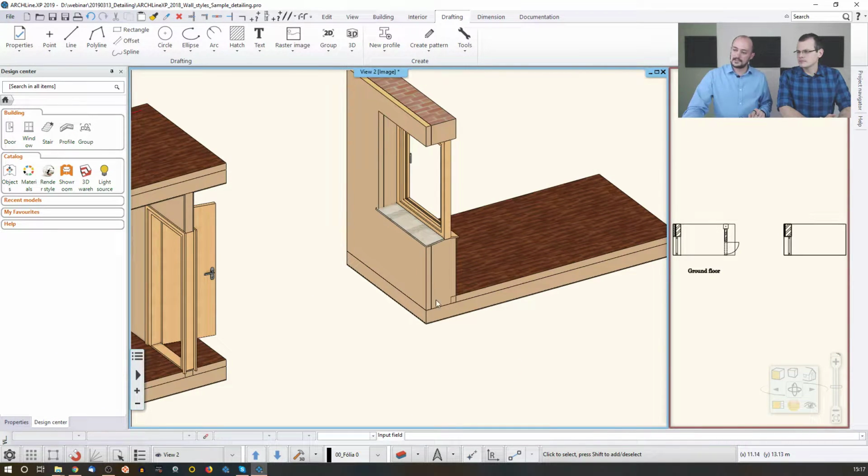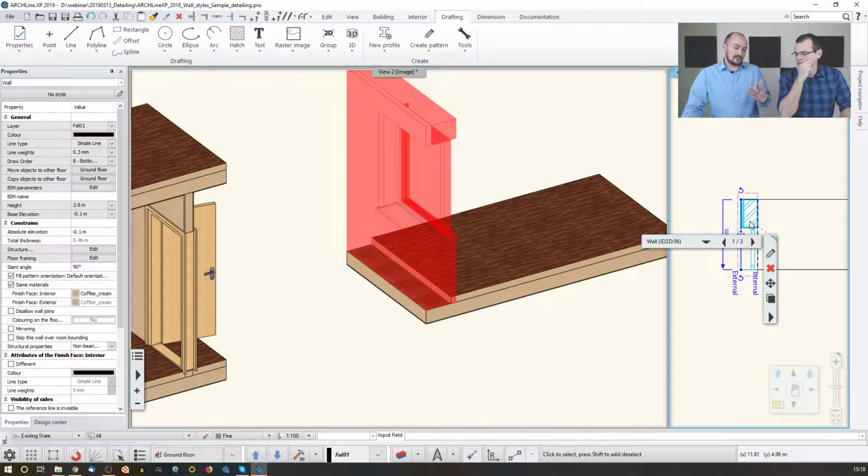Okay, so now I have this, and in this case, just to again deeply understanding how I am doing this, when I created this drawing, I created, just as most of the architects would do, I created it with its outer contour. You can change this to the core layer or something like that. I usually create it by drawing the outer contour because that's usually something that I have to stick to. And whenever I make changes, I should not make my building bigger than the expected size. So that's why I drew it like that, and that's where you can see the reference line.